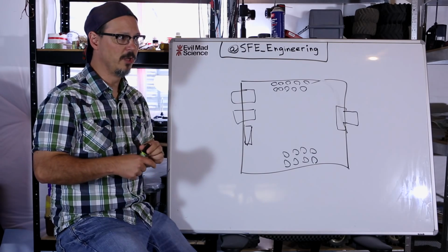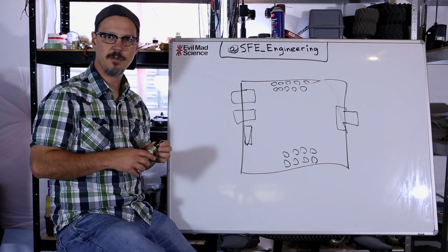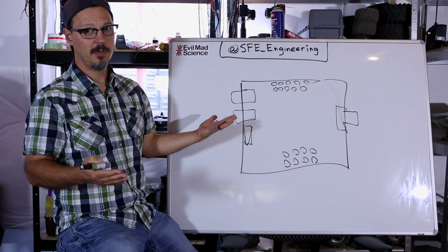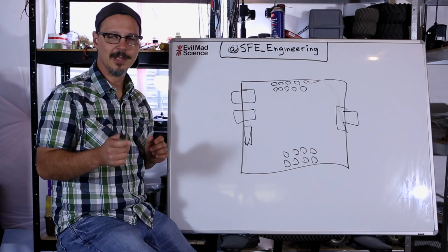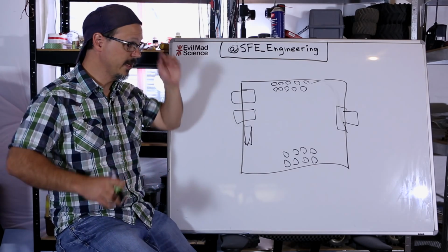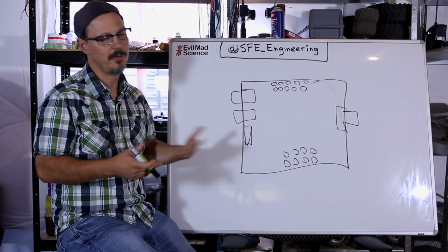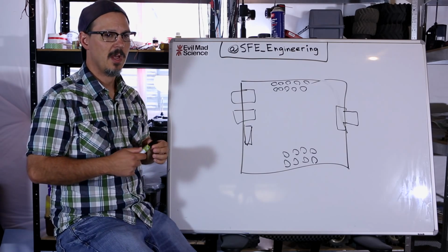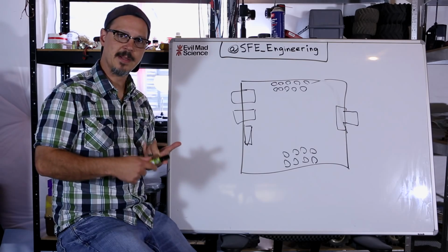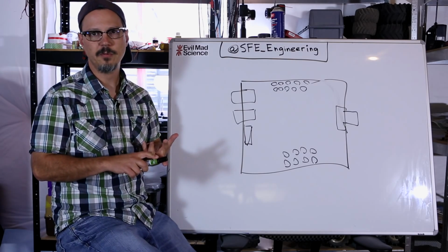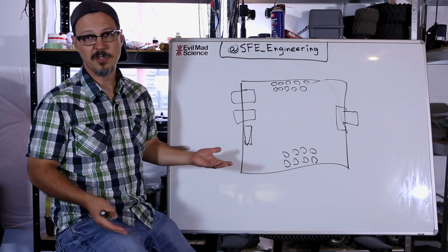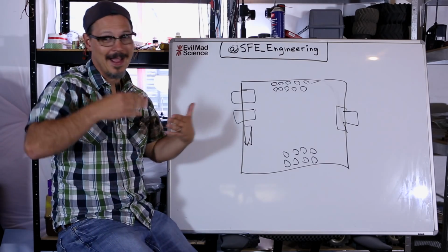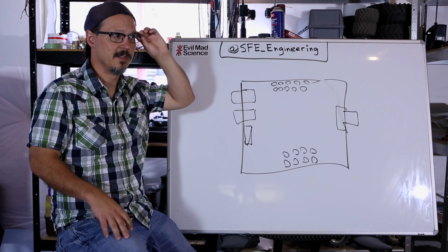At SparkFun, we use 1 ounce copper pretty much universally because it's cheaper and we can get the job done pretty well that way. Then, of course, we should talk about how many layers your board has. Now, we do have a few 4-layer boards, but 4-layer boards tend to be more expensive. So we generally do everything with a 2-layer board because it's inexpensive. And most of the circuits we do are easy enough to do as a 2-layer board, but we do use 4 layers in some cases.